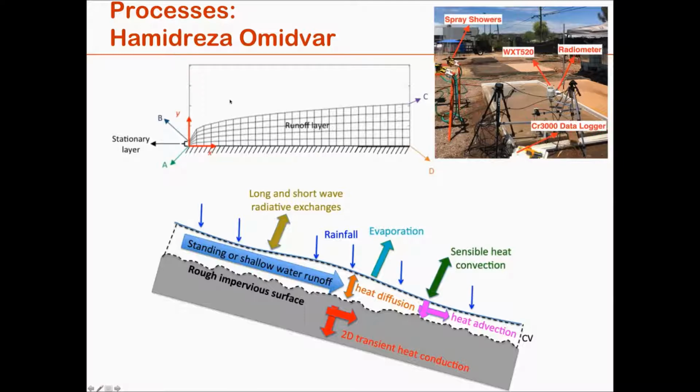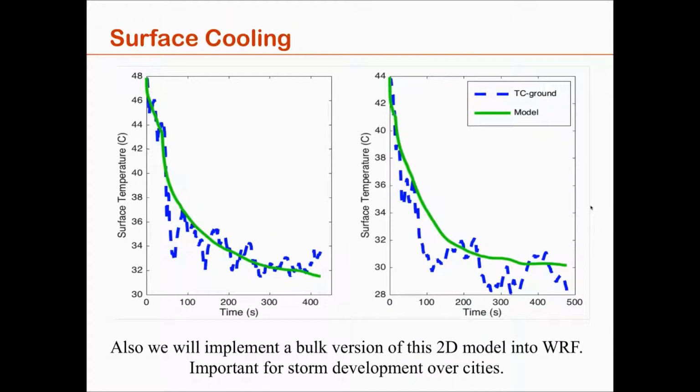So we've modeled this numerically, and we also did some experiments over the campus of Arizona State University with Jiwa Wang. Again, they have these very nice experimental pavements: impervious concrete, impervious asphalt, pervious asphalt, and here you cannot see it, but it would be the pervious concrete. So we have 4 different kinds of surfaces, and the initial validation of the model is very promising.